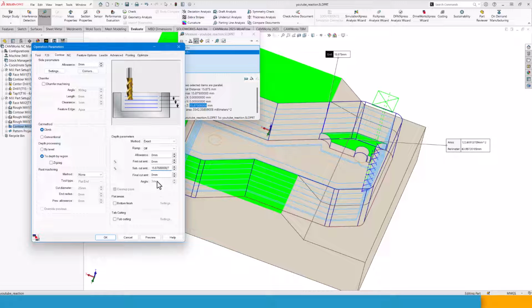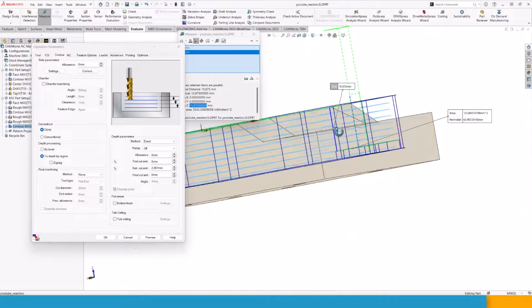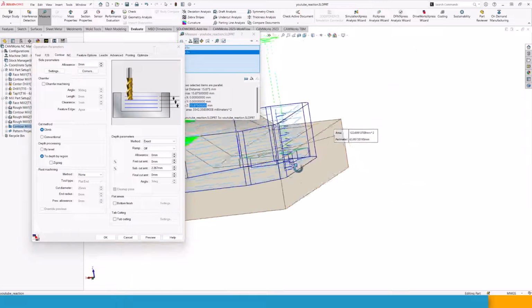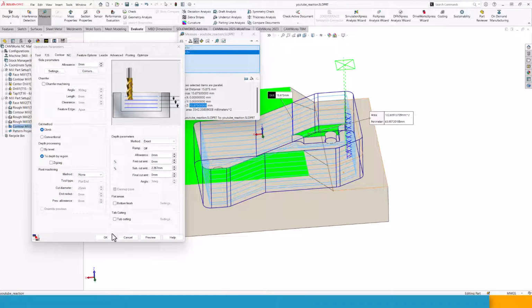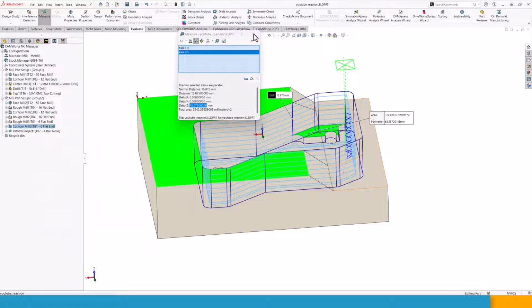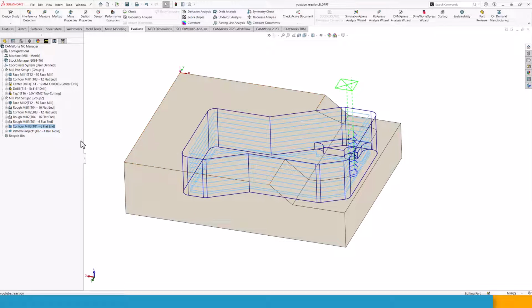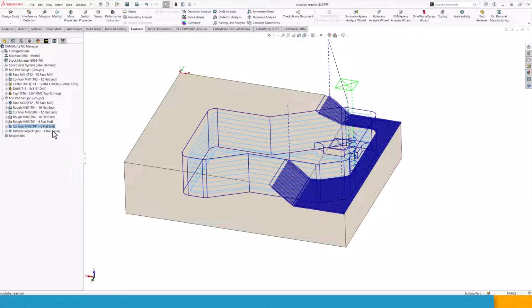Maybe you want to have 7, and then just click outside. And when I do this, I tend to remove one digit. In this case, I'm just going to change the 8 to a 7 and then just preview. And this should give a toolpath very, very close to the top, so we are cutting this part like we want to. So that is the first part of it. Let me close this one. So actually, in that you already saw there was a trick. You can use mathematics in your dialogues. That's very good to know. You are in SOLIDWORKS, so obviously you probably knew that already, right?